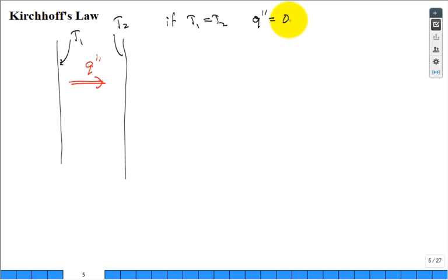0. You're correct. What's happening is you do have emission coming from this one. And so let's call that emission from 1. But where does the emission from 1 go? It can only go and hit 2. Radiation goes in a straight line. The photons just go straight until they hit something and interact some way. So from the perspective of 2, guess what G2 is, the incoming into 2? It's equal to the outgoing from 1.